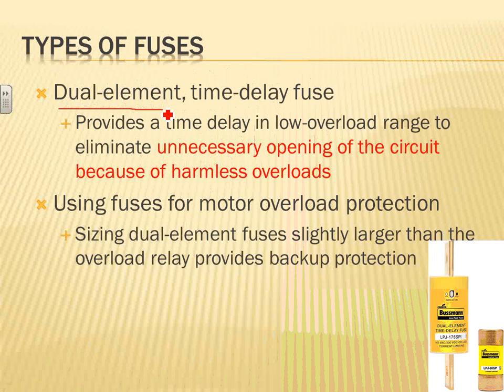When we design a 4,000 amp switchgear with an 85 interrupting rating, that's one assumption, assuming that this equipment will be maintained properly for the life of the equipment. If the equipment is not properly maintained, then that switchgear with the 85,000 interrupting rating might, over time, go down to 70 or so. So unless you maintain it properly, and that's where maintaining the power system properly becomes a big deal.